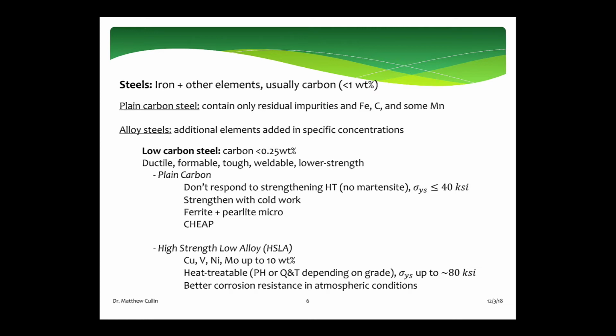So I think one of the more popular grades of low carbon steel that you come across is A36. ASTM is the group that writes the standard that governs the material, and then 36 represents 36 KSI yield strength. So when you go down to Alaska Steel and you buy some random steel products, if you don't ask for anything special, you're probably getting A36.